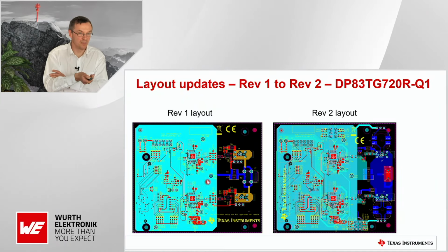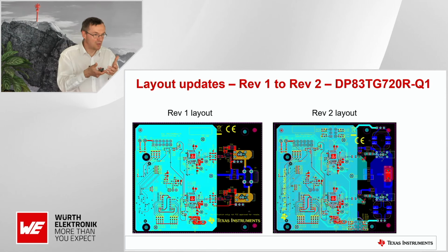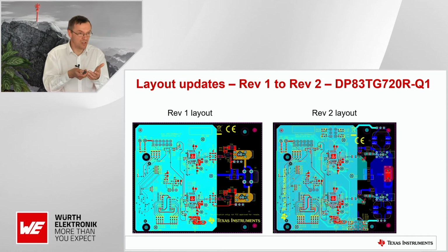Now, also what I wanted to show is from a layout perspective, of course, this is the first test. What you see here, these traces here, they were basically too thin to hold the surge current. So what we saw was they blew up when we went high enough in the surge. And that's why you see on the second version, I did a polygon plane, which I should have done in the first place, but I didn't. But we know now why I should do it.